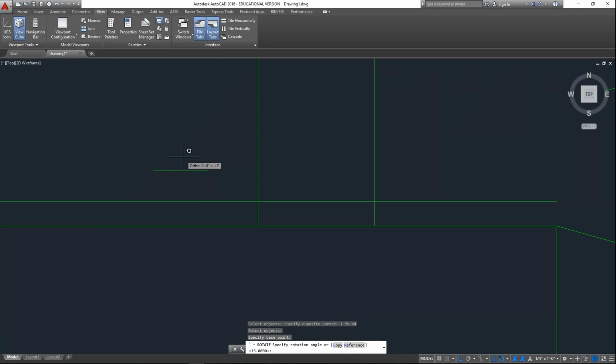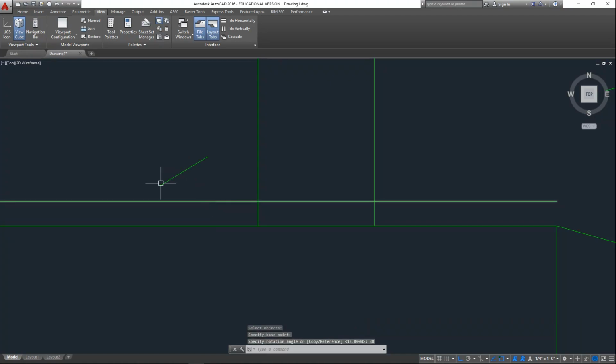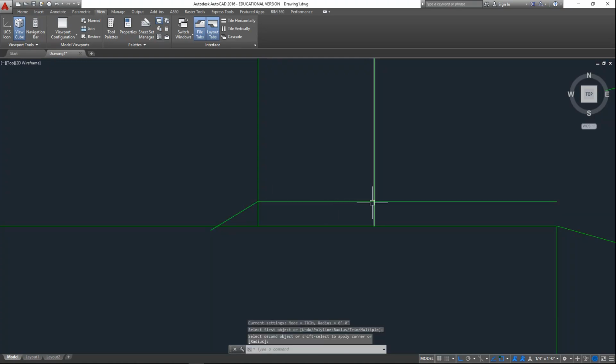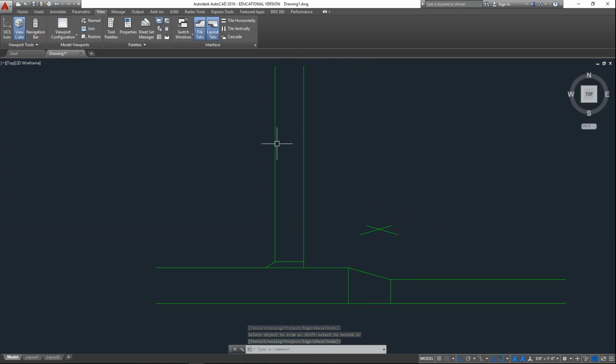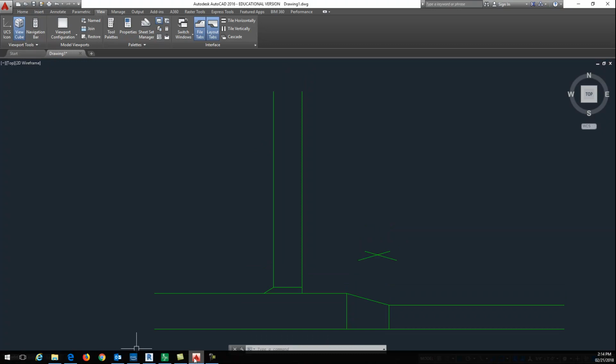that is 45 degrees. See how that looks. It's a little steep for a transition. I think I'll do 30 degree. See how that looks. A little bit better. So I'm going to take that 30 degree line and move it to there, and I'm going to fillet this and that. I'm going to trim that off, and that section. Now I have that section of ductwork started.